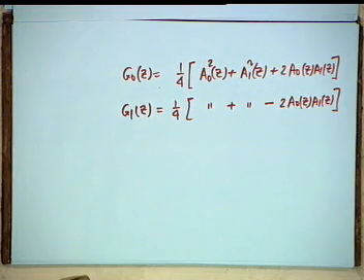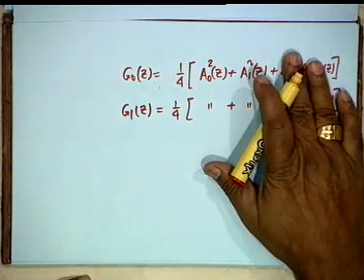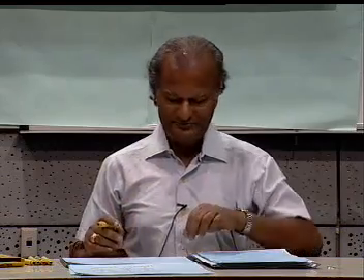Are they all pass complementary? If we add them, do we get an all pass filter? Not necessarily. In general, no. Are they power complementary? No. They are magnitude complementary. Okay? So, having a triple complementary filter, unless you take very trivial examples, is a very difficult problem.